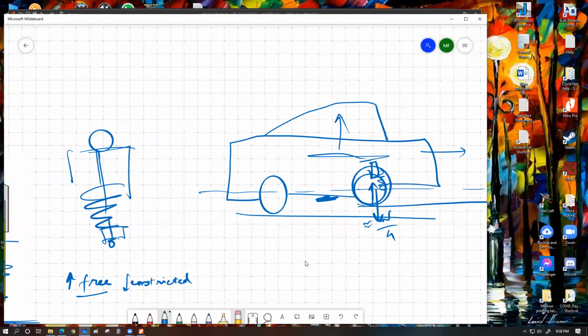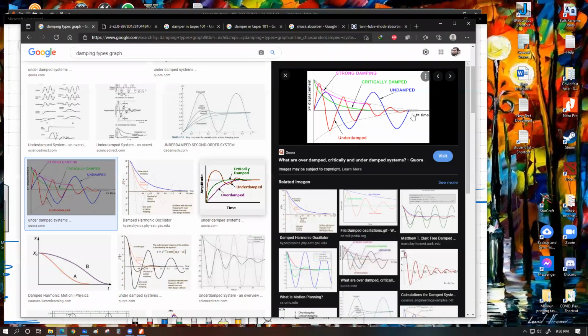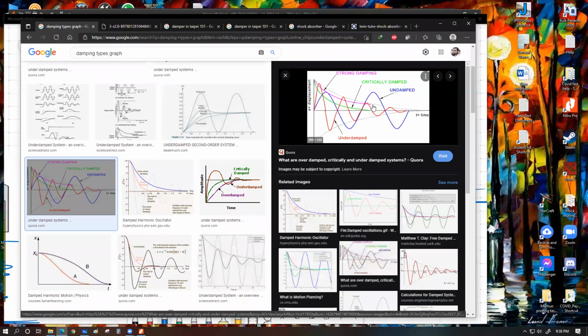These types of systems are what we call overdamped systems. They take out the energy almost immediately, then release the energy over a significantly long duration. As a result, the vibration cannot continue. You can have a lot of different graphs for the overdamped system. For example, in this case, they haven't even shown this graph reaching equilibrium, because it might take a significantly bigger amount of time for the oscillation to be released.